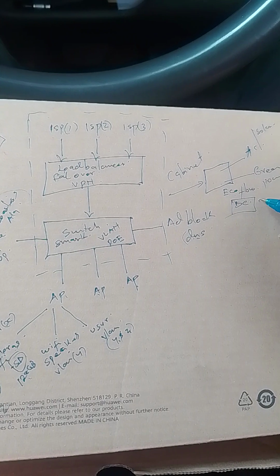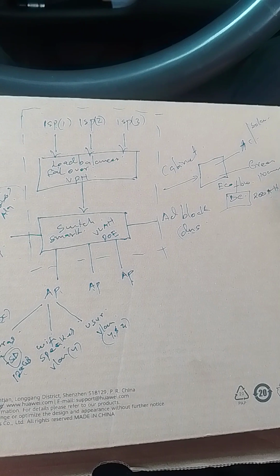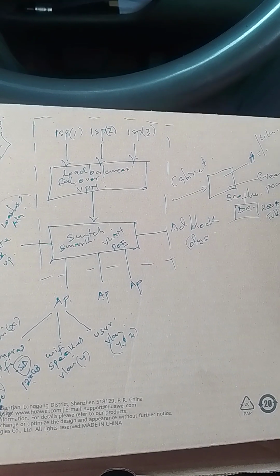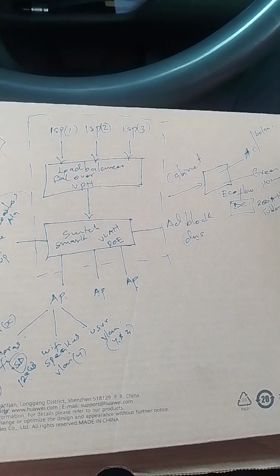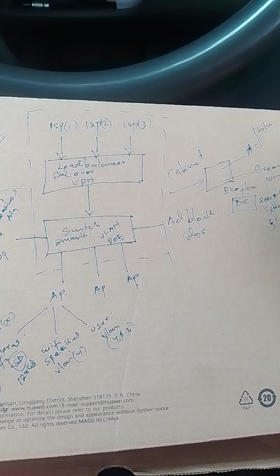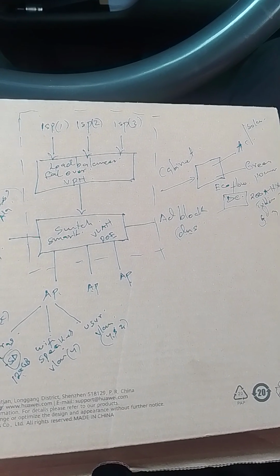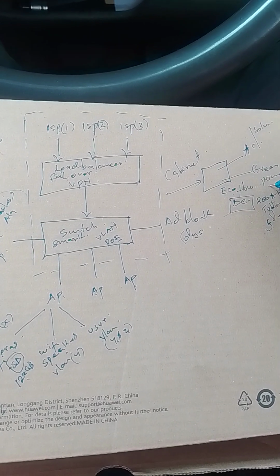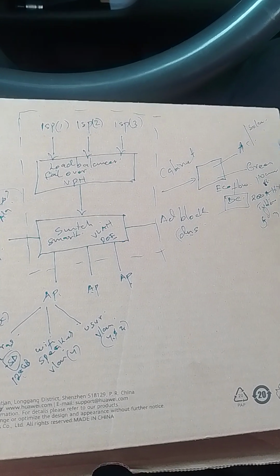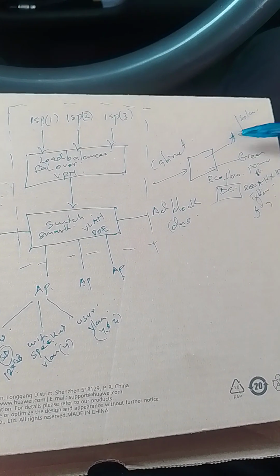Now, these ones are the 200 AH batteries, tubular, which can last us, we are talking about 10 pieces, which can last us up to 4-5 days. Say 5 days, so we'll be good without Kenya Power coming back. Plus, we have up to 8 hours of sunlight. So say 6 hours of sunlight. So mchana, these batteries will charge either way. So we can even stay longer without the AC.